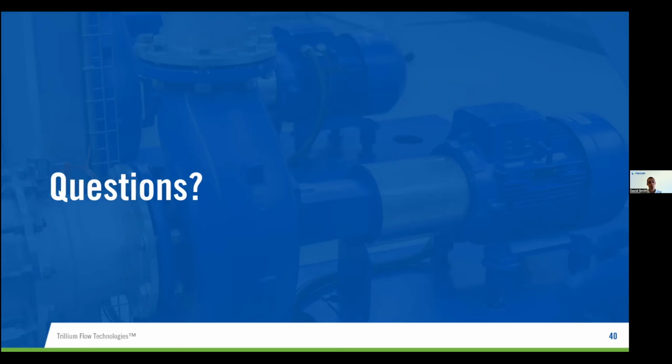We would then do similar to what we've just spoken about with the re-rate, and come up with the required parts. We've recently done that on a single stage unit for a customer who only wanted to change the impeller to reduce the best efficiency flow rate as best they could without changing anything else. So we essentially did a new design of impeller using all the scanning techniques, with the capability we have in hydraulic design and CFD. I think this leads on to the next question, which is testing.